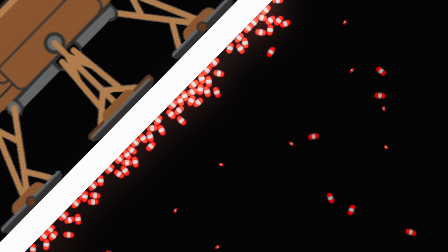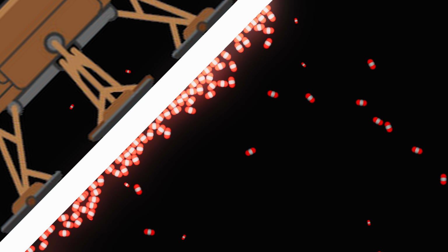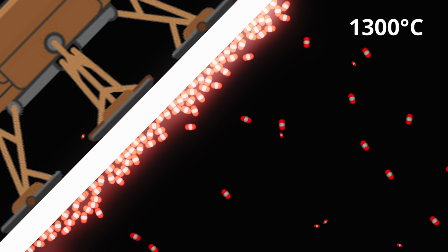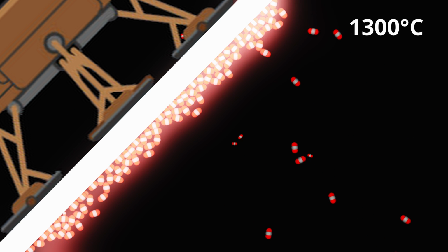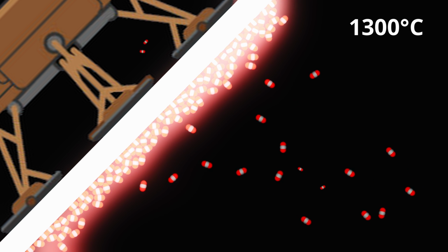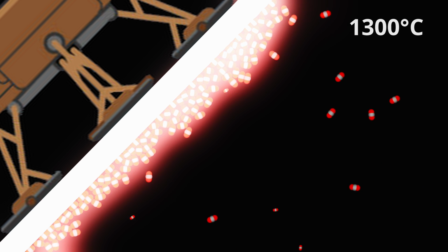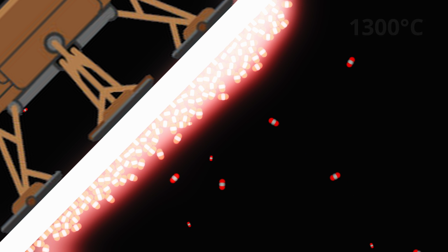As a result of this, the air molecules pile up in front of the spacecraft. In essence, the air in front of the spacecraft is compressed. And whenever a gas is compressed, its temperature will increase. At the speed that our spacecraft is moving through the air, this increase in temperature is a lot, about 1300 Celsius at peak heating. This amount of heat will destroy any spacecraft. Since our windshield is in front of our spacecraft facing the incoming high-speed air, that's where the compression and heating will be. So to prevent our windshield from being destroyed or transmitting the heat to our spacecraft, we must convert our windshield into a heat shield capable of withstanding these high temperatures.